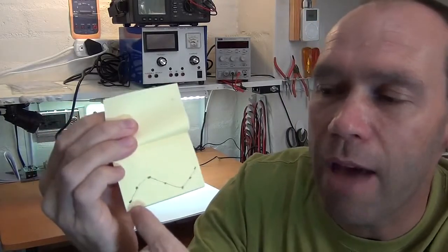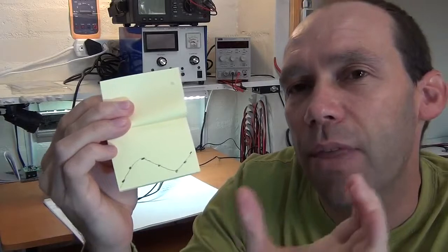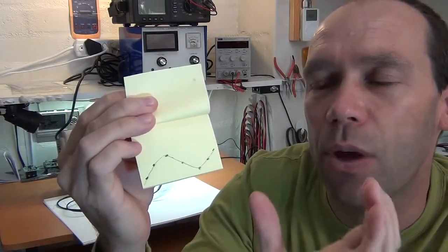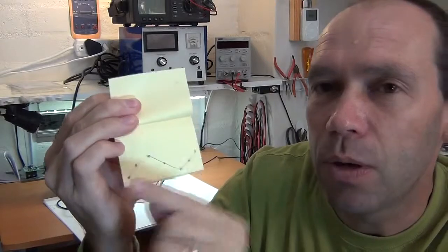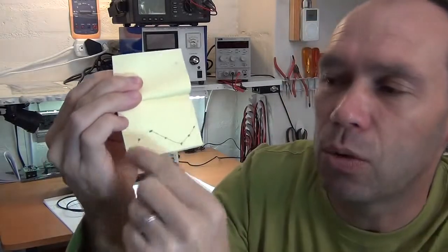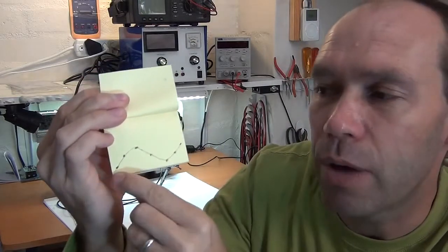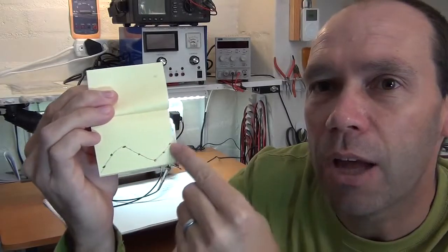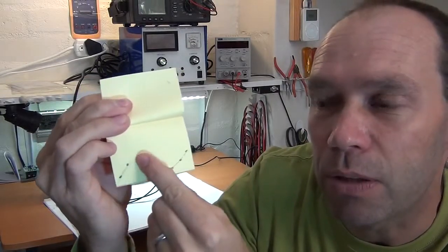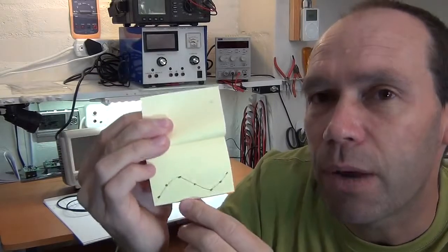And in essence, that's exactly how the old analog oscilloscopes work. They used those old CRT tubes, cathode ray tubes, and it would alter the beam, or the trace as it's called, as it got a signal. And because of persistence of vision, your eye, it would actually draw a trace and join the dots, or join the individual measurements, across the screen. And that's in essence how the original oscilloscopes worked. Although it's obviously different today with digital ones, they just have the signal and they plot it on a digital display.